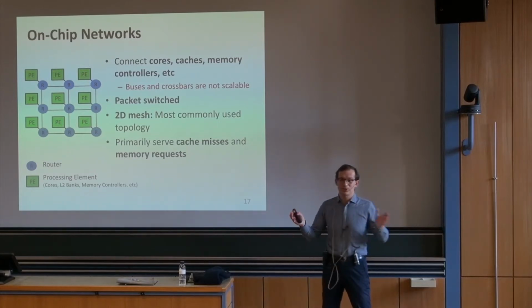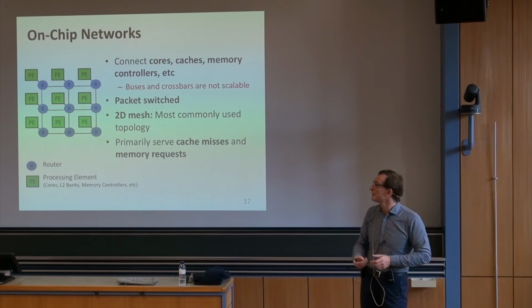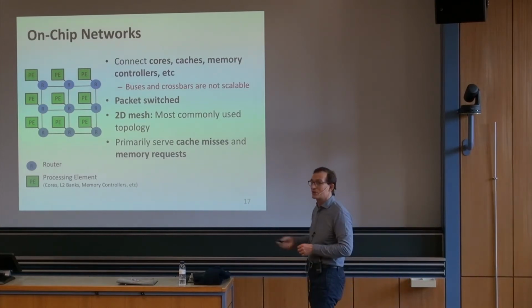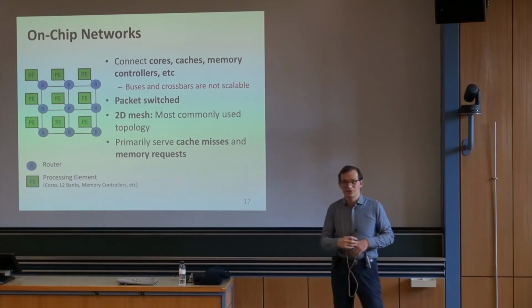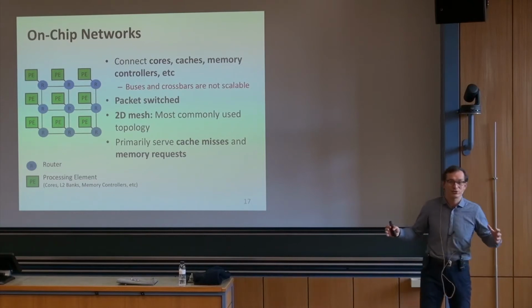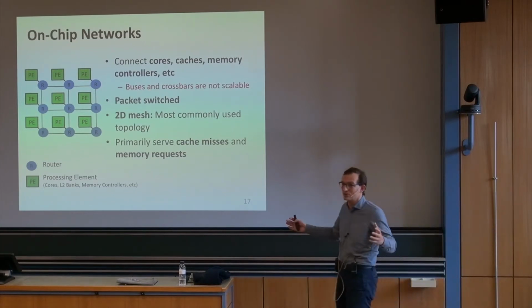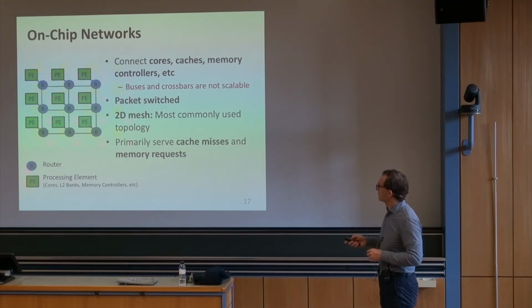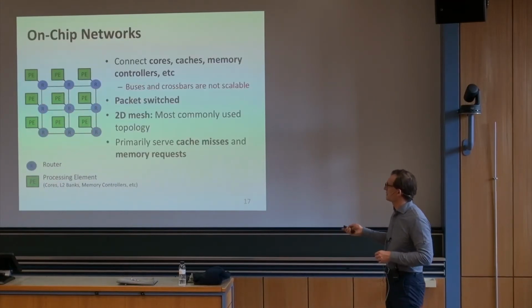But if you have the MESI protocol, if you're modifying your data exclusively, you know that nobody else has the data, so you don't actually need to send a coherence message to anybody else, right? Once you have exclusive access to the data that you're modifying, you don't need to keep it coherent. Okay. So certainly there's coherence requests over here that should be added.